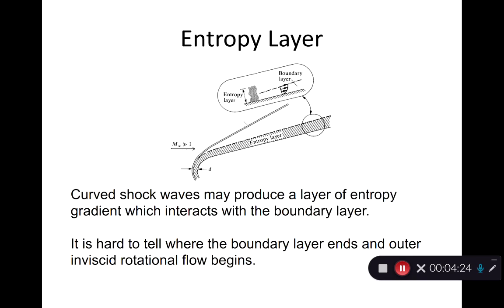The second aspect of hypersonic flow is that because the shock is curved over, especially for blunt bodies such as re-entry vehicles or a blunted cone in the case of a re-entry missile, behind the shock wave, the flow may be non-uniform because the shock angle, beta, is different. We studied in our conical flow that the conditions behind the shock wave depend on the shock angle beta, and therefore different turning angle will occur, different layers of slowdown will occur, entropy jump will be different.